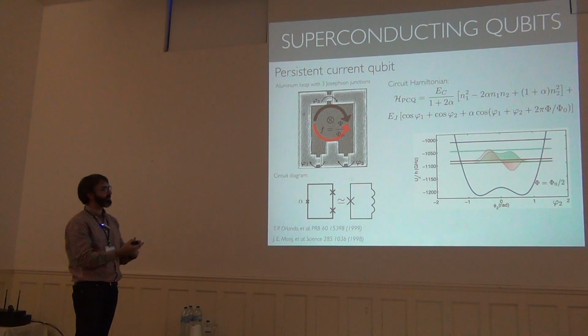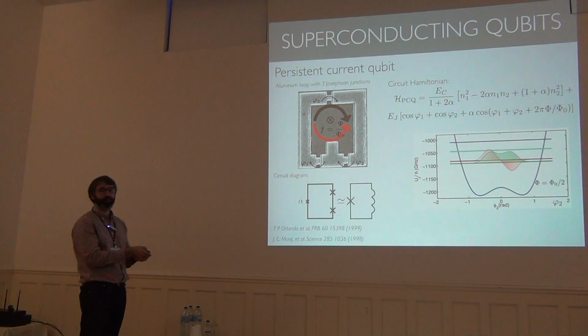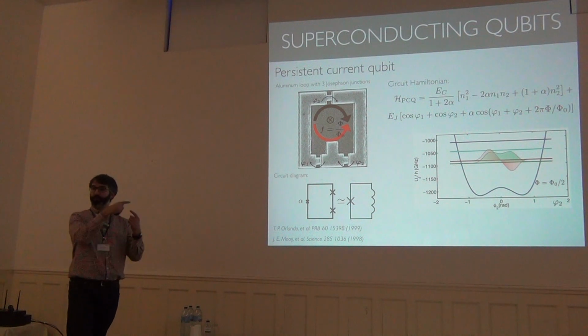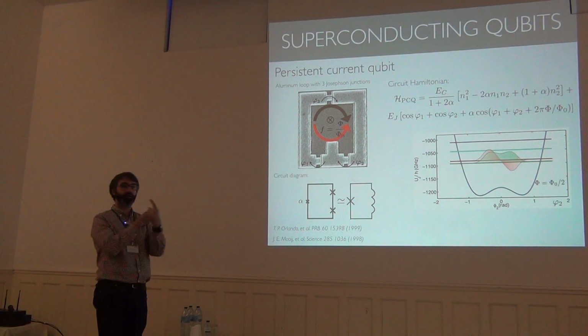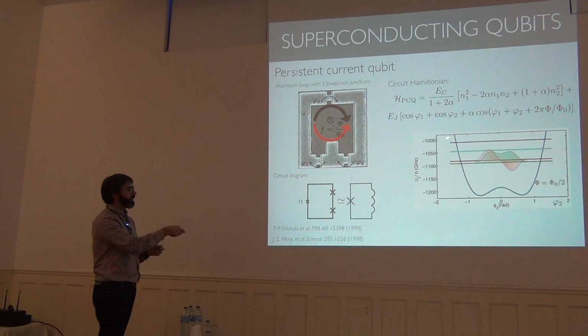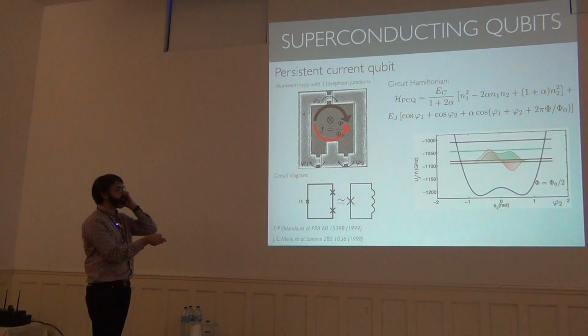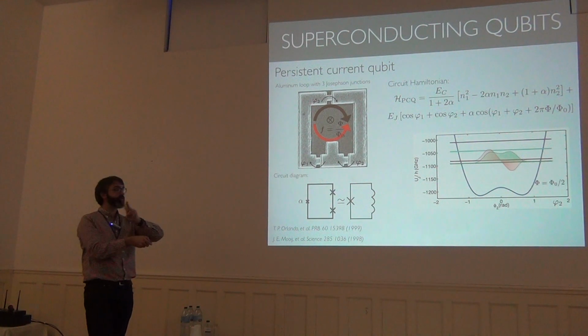But if you minimize your energy classically, you find that when the flux is near half a flux quantum, this point that I was telling before, where these two currents are degenerate, then the potential energy is the double well potential. And these are energy levels, so this is already solving this Hamiltonian. And this is the wave function of the lowest 2 states.